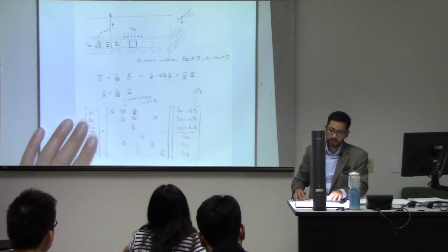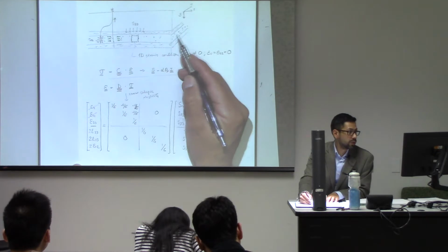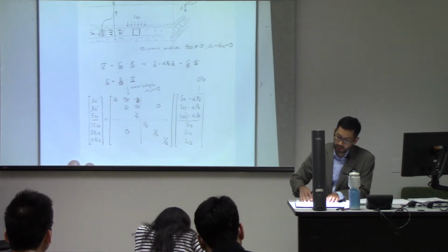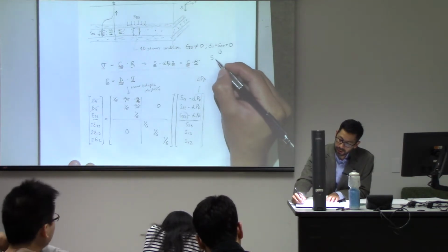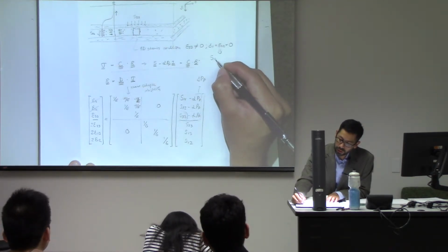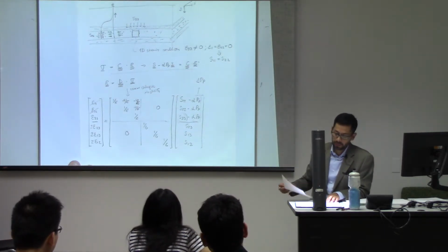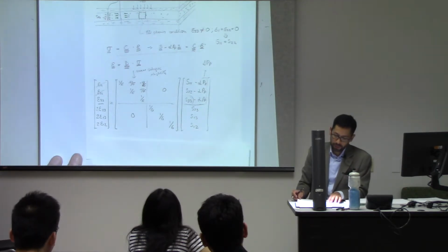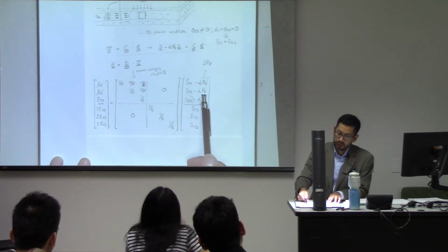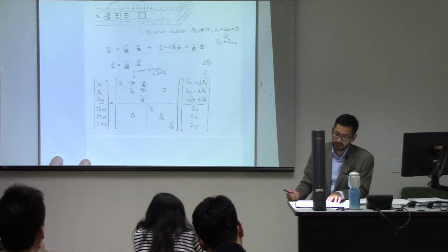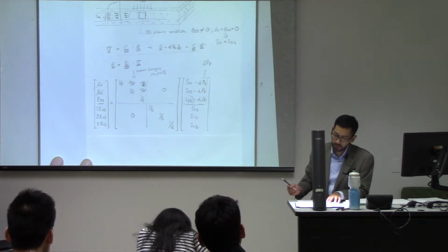So if that's the case, there is not going to be strain in this direction, there is not going to be strain in that direction, and therefore S22 and S11 are going to be the same. All right. So these two are going to be the same, right? And let's just write it in terms of, let's say, S22, because I'm interested in that one over there.